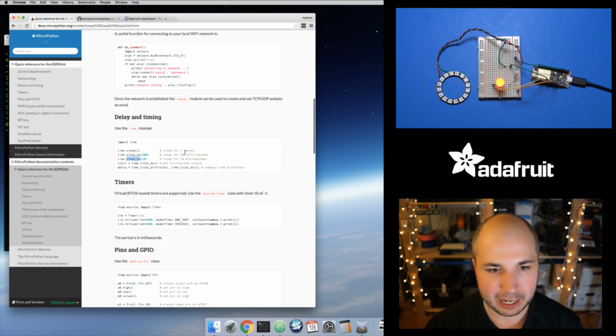Those are useful because the ESP8266 has a little real-time operating system internally, and you don't want to sleep for a long time without giving that RTOS some cycles back to do what it needs to do. It needs to take care of Wi-Fi. There are certain asynchronous events to stay connected to the access point and to handle connections and things like that. And there's only one core on that chip, so you don't have multiple cores. You can't just give one core to talk to the Wi-Fi radio and another core to run your program. Maybe future chips like the ESP32 might be a little better about that. But because of that, you have to be careful. You can't just go into an infinite loop, or else the chip will reset itself.